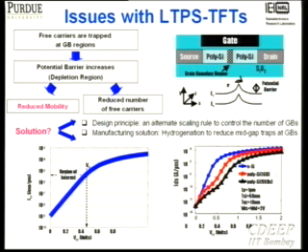So what we really did is that I know that I have another constraint: I may not be able to use high temperature. If I'm not using high temperature, my oxides may not be of the best quality, so I have to be worried about that too. The issues turned out to be that the free carriers are trapped by the grain boundary (GB) regions. The potential barrier due to the depletion region is going to have the effect of reduced mobility on these transistors and a reduced number of free carriers.